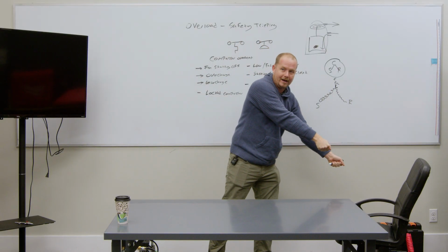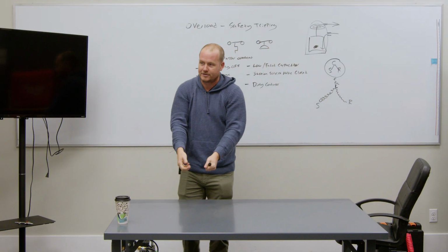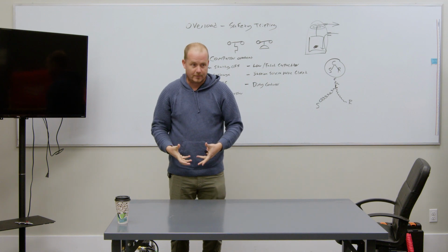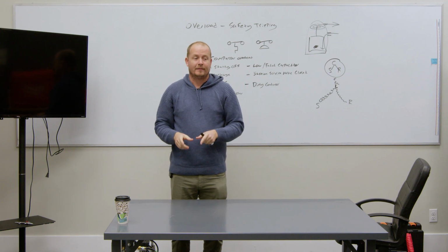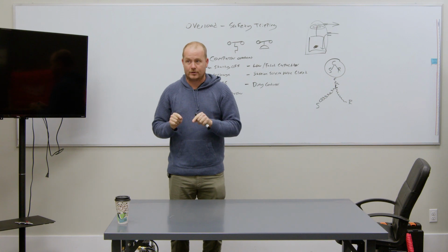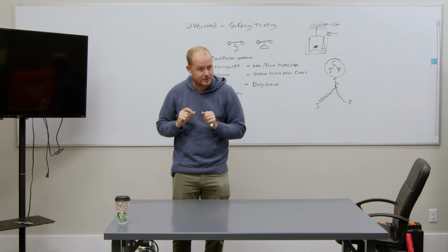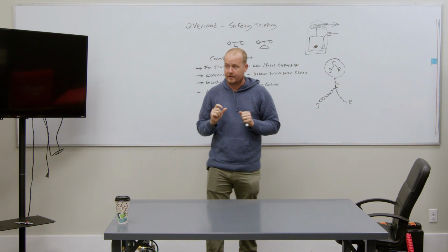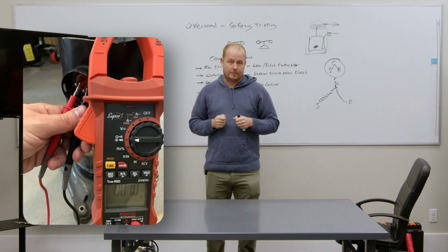Unwire it, put it in the grass, go down to the compressor, open up where the terminals are, and inspect the terminals. That's the main reason why, and then I want you to do these tests at the terminals. If it's individual connectors, take a picture of it first to make sure you don't miswire them. Same thing with the fan. If you're new to it, just take a picture real quick, unwire it, and do it at the terminals.